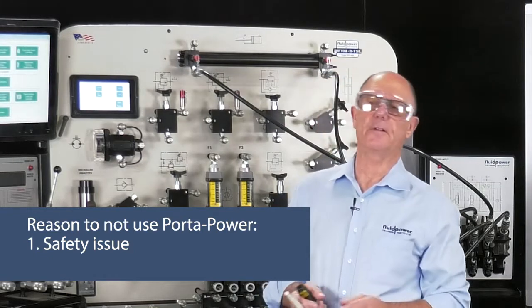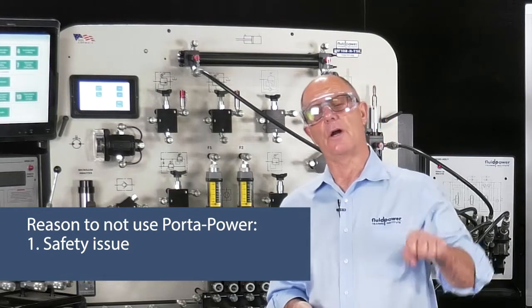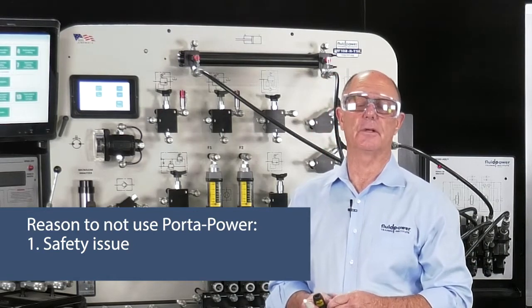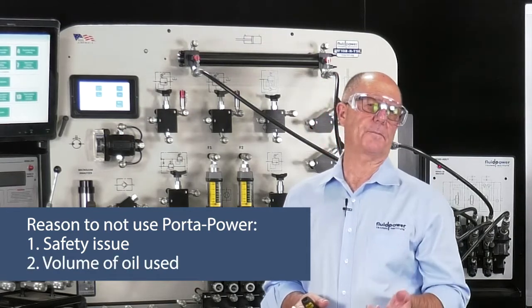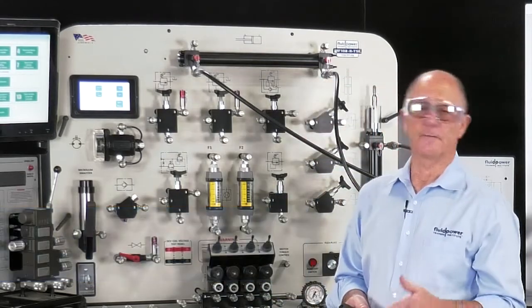So if you're testing a 1,500 psi check valve with a 10,000 psi valve, one stroke of the handle will put you at 10,000 psi. I think that's going to be highly dangerous. Number two, what is the volume of oil that this Porta-Power is producing? Could it give me a false positive or a false negative?